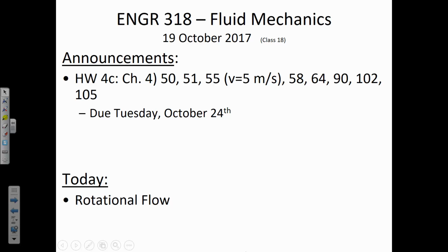What kind of acceleration were we experiencing with the Venturi? Convective acceleration, which is where there's a velocity change with respect to position, right? Velocity is a vector with two components: magnitude and direction. Since the flow was all going in the same direction through that pipe, it was the magnitude of the velocity that was changing. And so Bernoulli's equation is what we use to characterize how pressure is affected by changes to the magnitude in velocity.